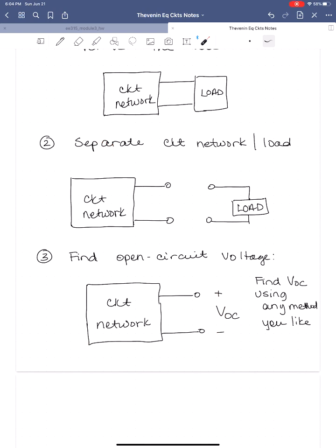Okay, so once you find the open circuit voltage, we set the Thévenin equivalent voltage source to that open circuit voltage. Now, oftentimes I get questions about the relative polarity of the open circuit voltage. What's important here is to remember that whatever the node or terminal where the plus sign of your voltage is versus the minus sign of your voltage, is reflected back on the load.